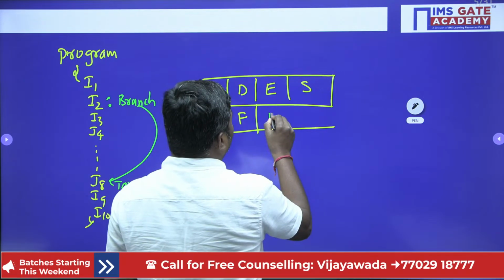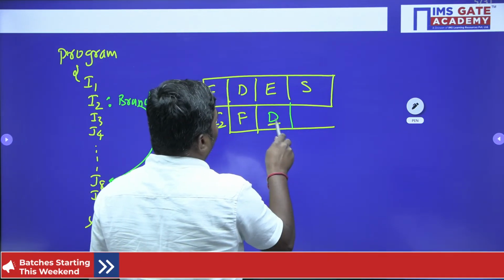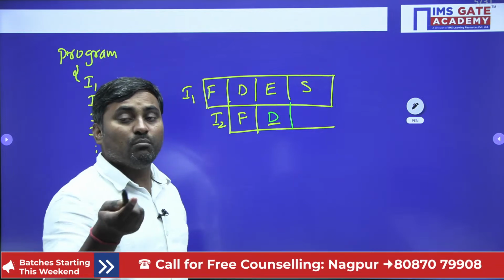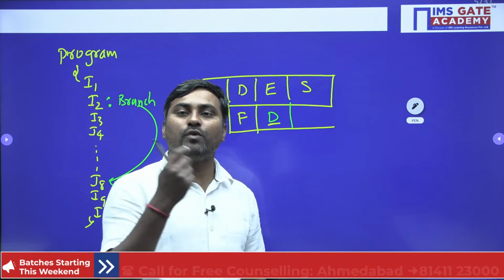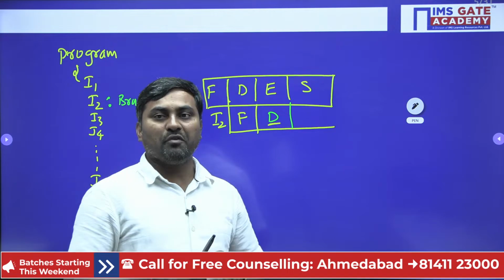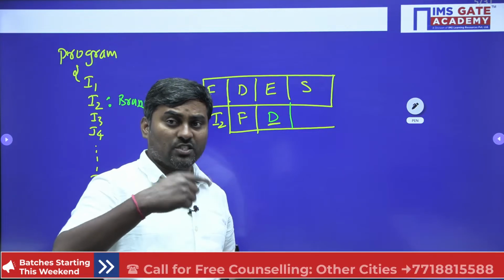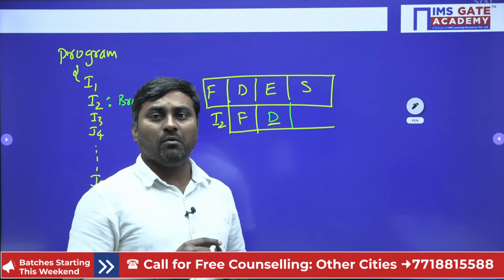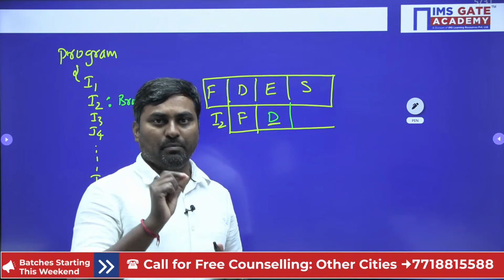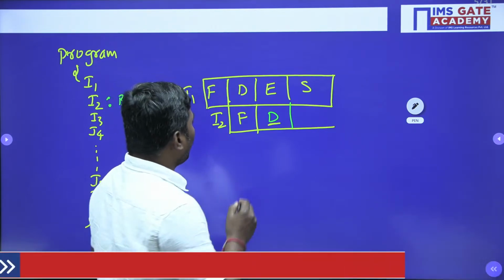Normally, please observe, during the decode stage we modify the data path. At the end of the decode stage we have to decide whether the sequential instruction or the target one is to be fetched. But to reduce the branch penalty further, you have to anticipate here.